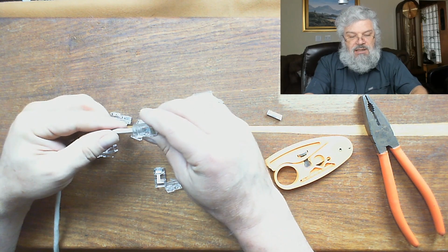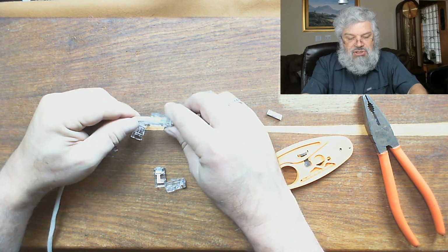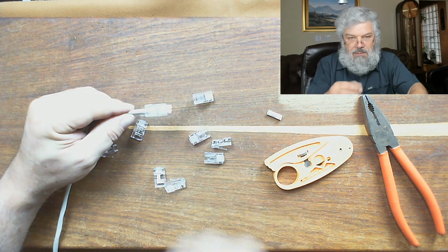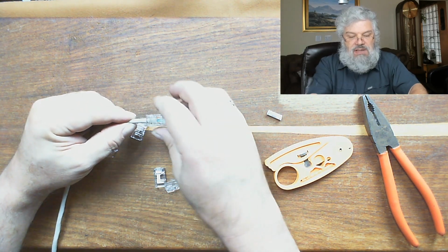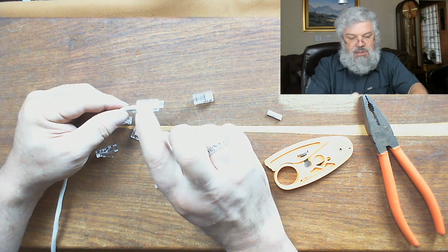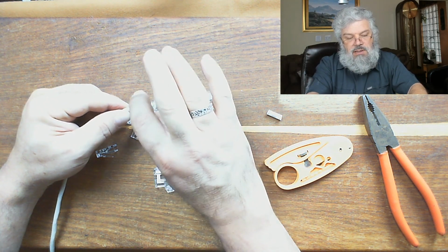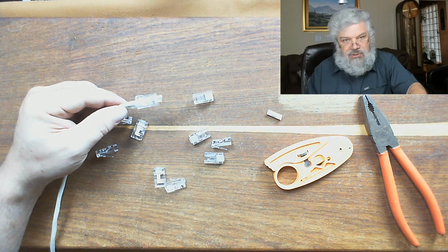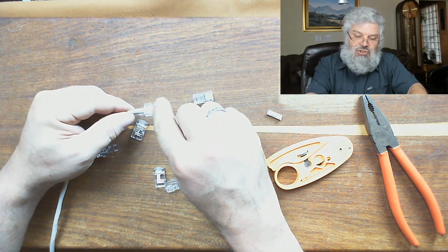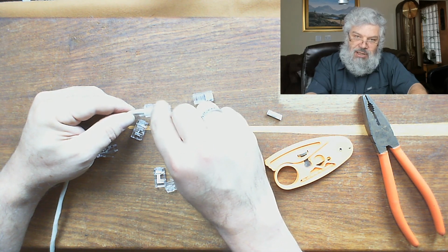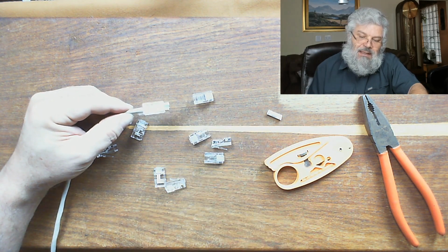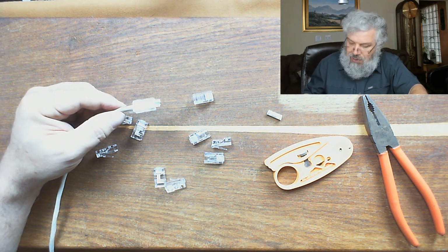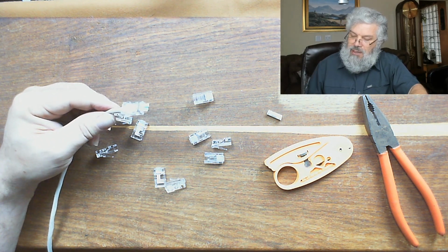So once I've pushed that in, I should make sure that the sleeve is pushed well into this part at the rear, because I am going to crimp it. I'm going to do 2 things to it. The one, while crimping it, is to hold the cable, and the other one is to push these copper contacts into the wire to make a secure connection.